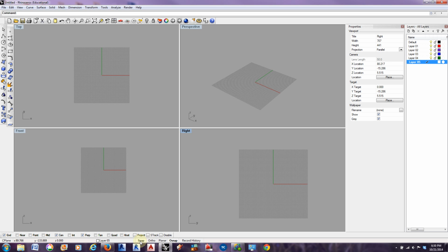So I'm looking to you. The snap itself turns on whether you're snapping to the grid or not. So if we were to select a line here and scroll in pretty far, you can see how it starts to snap to that grid line. I believe if I turn that off, it won't snap to the grid line anymore.